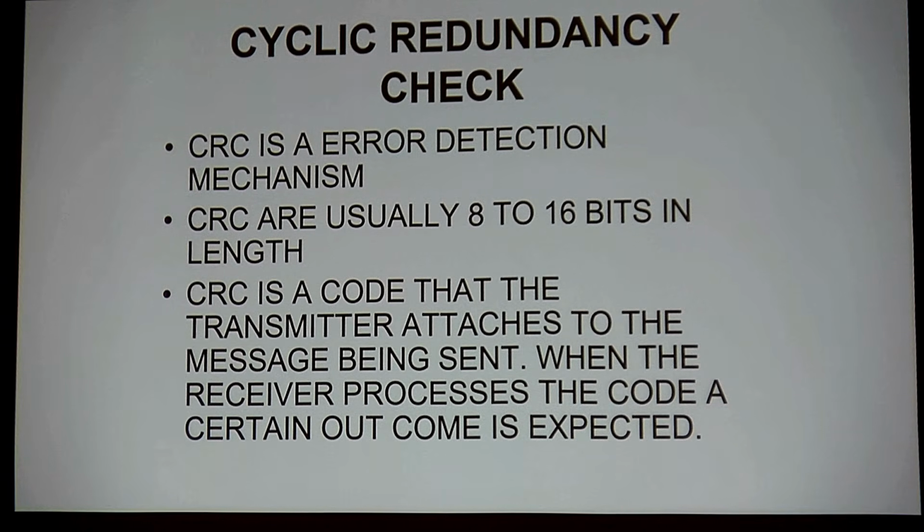Maybe we would want to do a speed limiting error because we thought we were going 200, so we would shut the injectors off to try to limit the speed. That would give me a problem. So we don't want bad messages on the bus. We need to contain the bad messages. The CRC is just a code, and it's going to go in and it's going to check it. Now, the other modules that are receiving the messages are also running those messages through their CRC. Again, this is in hardware and part software. And if they see that the 2 strings don't line up correctly, then I'm going to have a problem. They're going to say that the message is no good, and they're going to destroy the message.